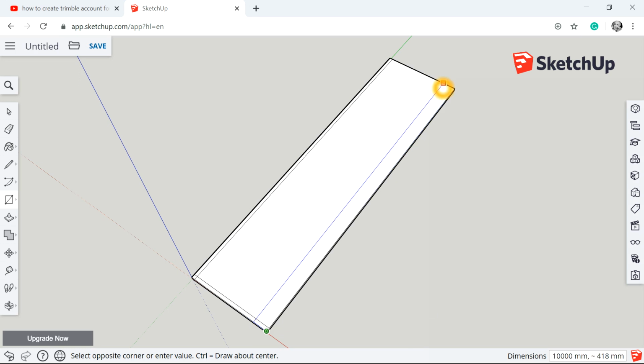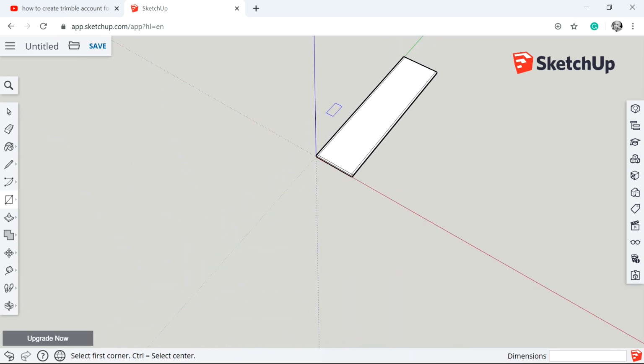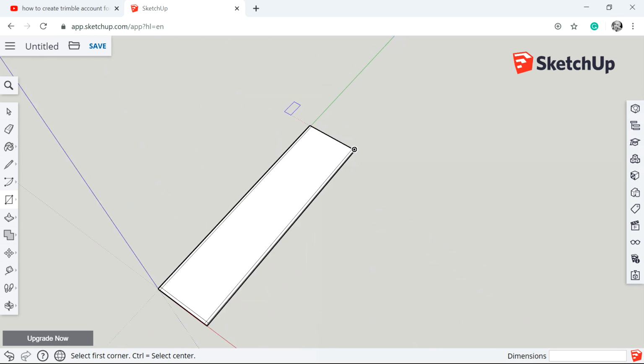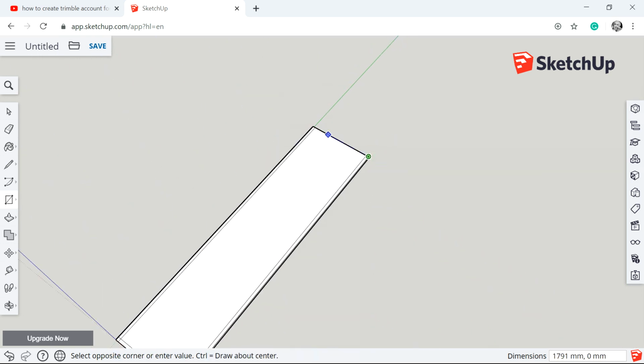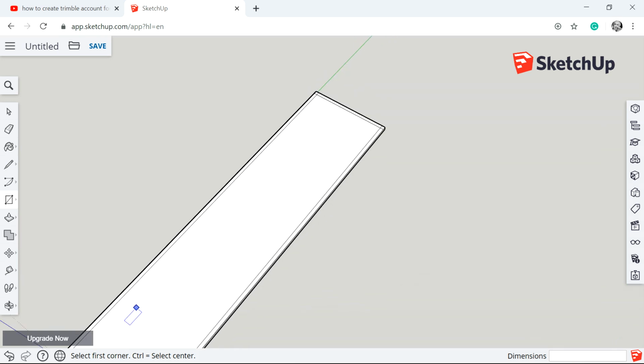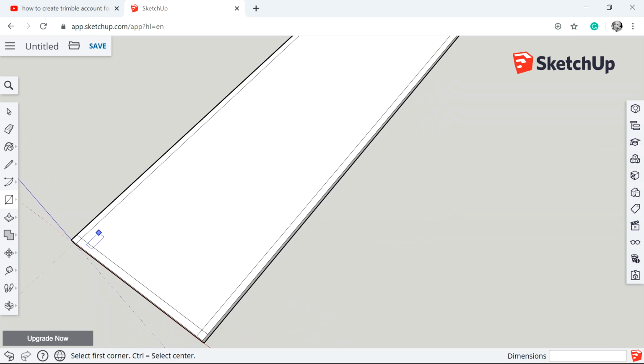So I want to put all my 4 walls on so that I know what space I've got. So that one will be 10,000 comma 100. Yeah, it's very important when you put the rectangle tool down. I'll show you guys just the last one. When I put the rectangle, I'll click first, but you don't give it a second click because then you'll lock it in place. So I'll click the first one and then I'll type in 2500 comma 100 and then enter that.